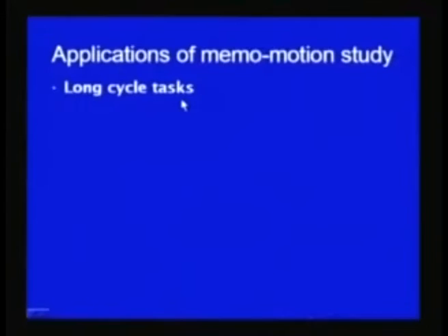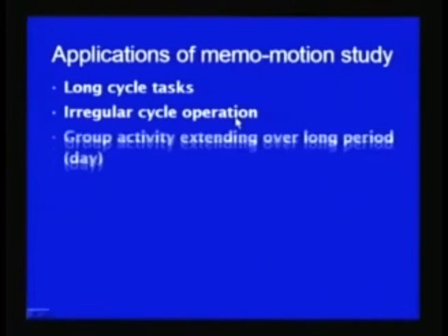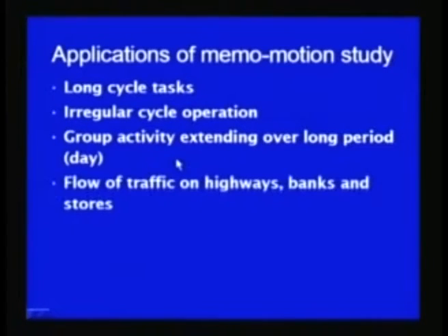The memo motion study can be effectively used for long cycle tasks which can continue for 2 hours or 4 hours. Irregular cycle operations can also be effectively studied. Group techniques extending over a long period, say a whole day, can be studied using the memo motion study technique, as can the flow of traffic on highways, banks or stores.